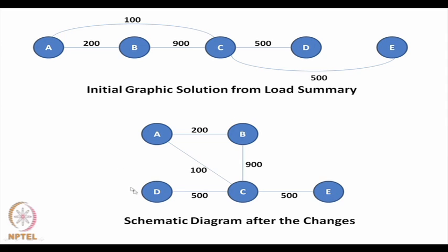So, this is a purely heuristic way in which we can put the relative location of the departments. The ones that carry the highest amount of material should be as close to each other as possible. The one that carries least can be a little away, the diagonal distance is higher than this distance. So, this is purely based on judgment.